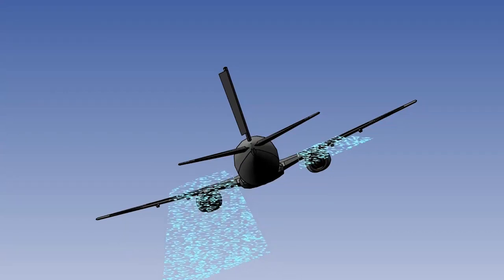It is safer to use the rudder only after the wings are unstalled, and then only to prevent further yaw if a wing has dropped because it has stalled slightly before the other. It is generally safer only to use the ailerons to level the wings, also once the wings are unstalled.